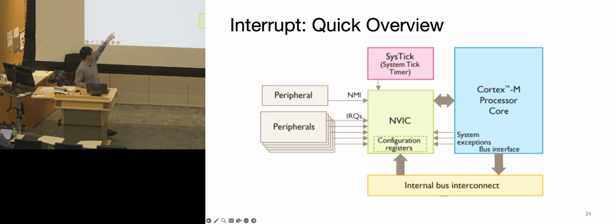Oh, and there's also the thing called NMI, which is also from peripherals, but it's called the non-maskable interrupt. It's a type of interrupt that cannot be disabled or masked. You can think of it as having even higher priority. It's reserved for critical events that require immediate attention, like hardware failures or system failures from that peripheral, for example. Typically not those events we talked about that we were designed to interact with.